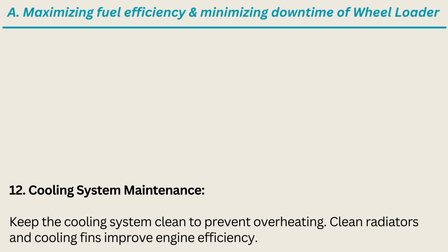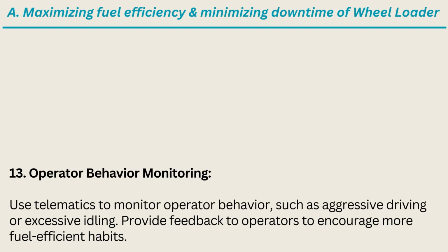12. Cooling system maintenance. Keep the cooling system clean to prevent overheating. Clean radiators and cooling fins improve engine efficiency. 13. Operator behavior monitoring. Use telematics to monitor operator behavior, such as aggressive driving or excessive idling. Provide feedback to operators to encourage more fuel-efficient habits.